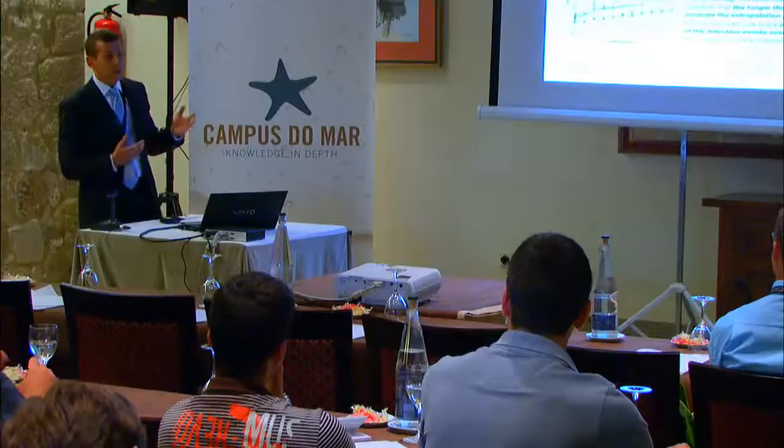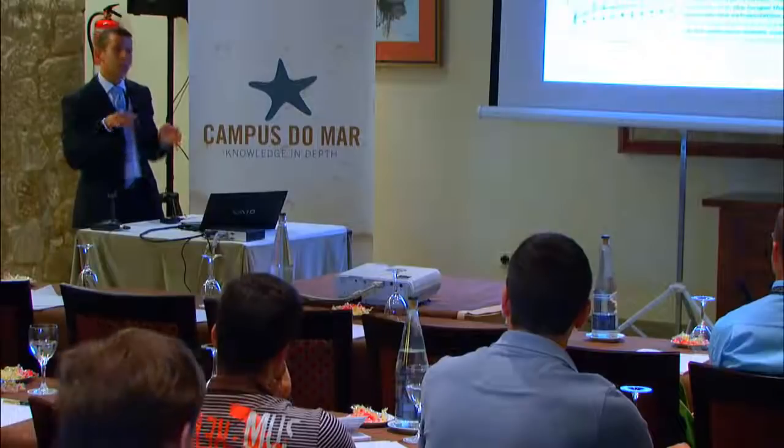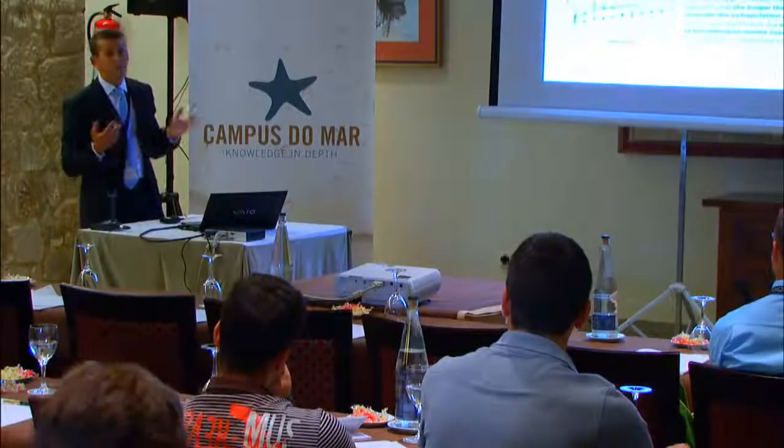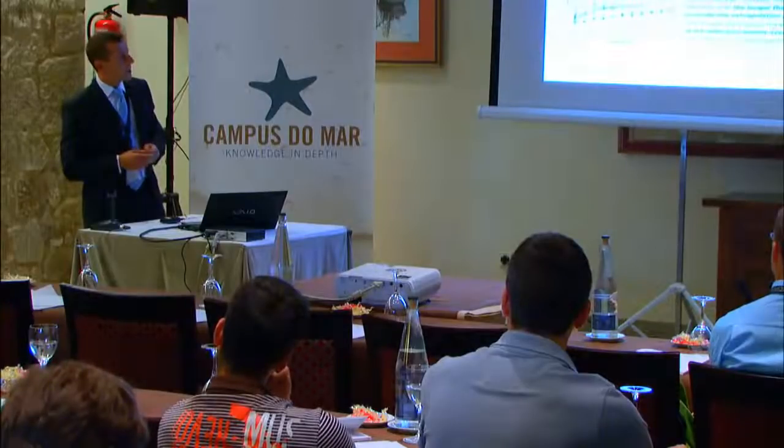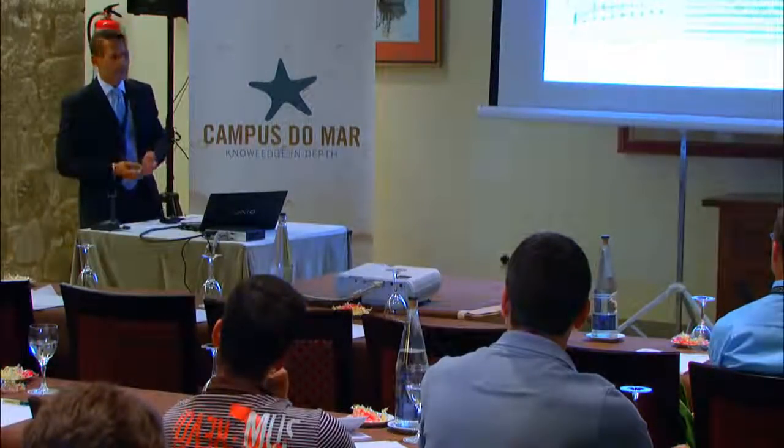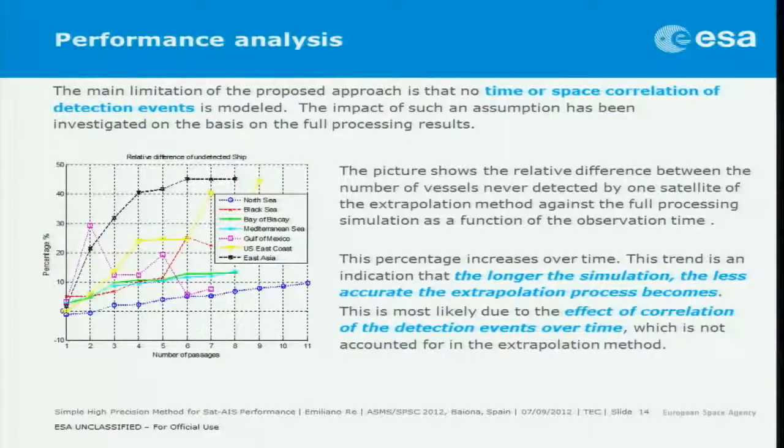The first analysis is about the time correlation of the detections. What we mean is that in our extrapolation, we are assuming that two different messages are, from a detection point of view, uncorrelated. Whereas in a practical case, it may happen that a vessel is in a very unlucky area, and you will never be able to detect it because you always have a lot of colliding messages. So what we assessed is, over the simulation time, the relative difference between the number of undetected vessels with a full processing approach and with our extrapolation.